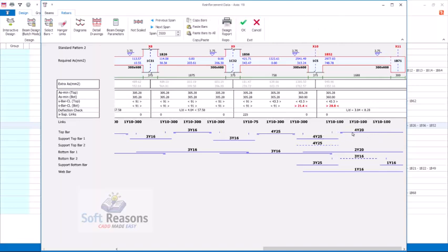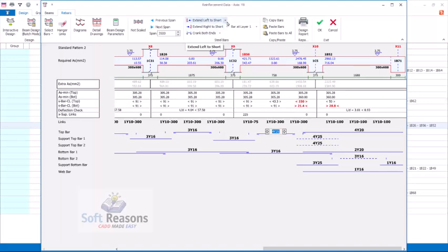Okay, after which, to correct this, you have to make this one a kind of first layer bar, and then this one now is going to be a second layer bar. Then here you have to expand it all across the slab just like this. Then over to this one, you have to also lap it and lap this as well. Okay, so you see we have corrected the top part of that.